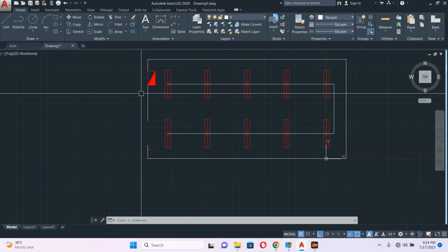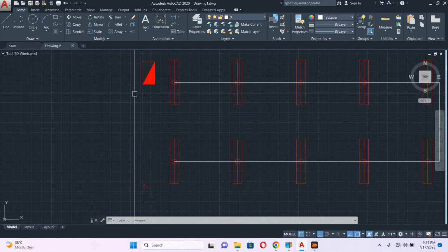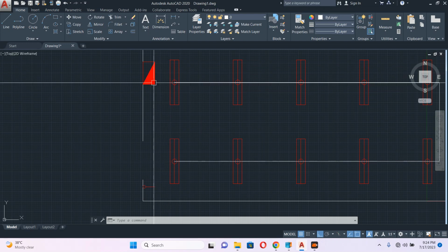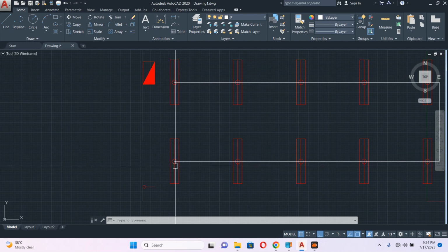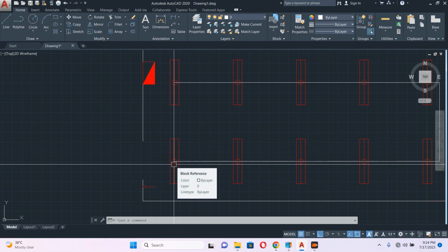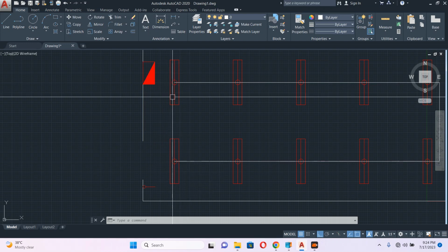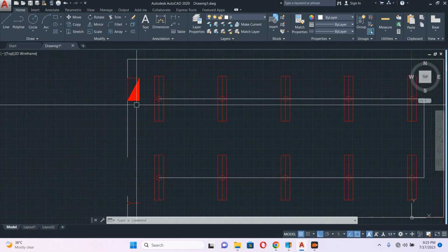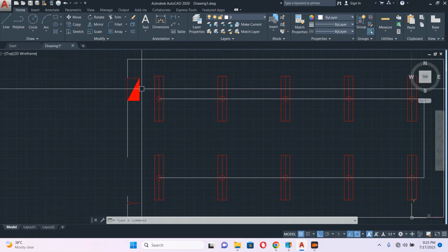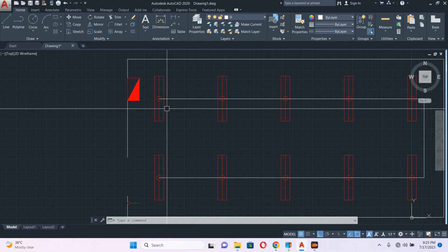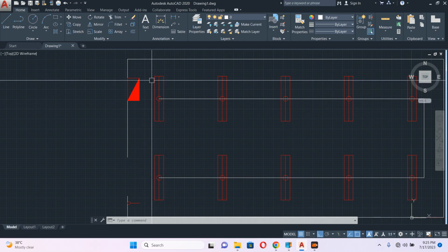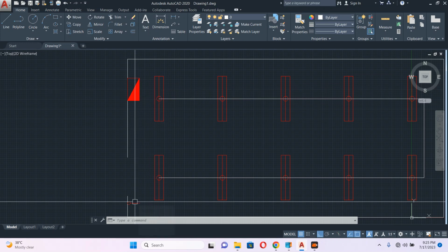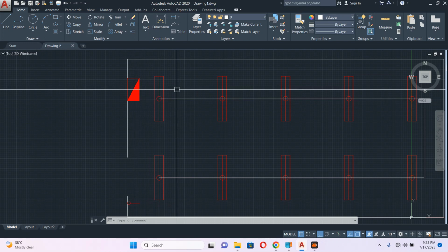So first you have to decide which one connects first, this light or this light, to the DB. If it is this light, you have to connect the switch first here. If it is this light, you have to connect the switch here. Why? Because the light has three wires: neutral, phase, earthing. The phase line first comes to the switch, then goes to the light.